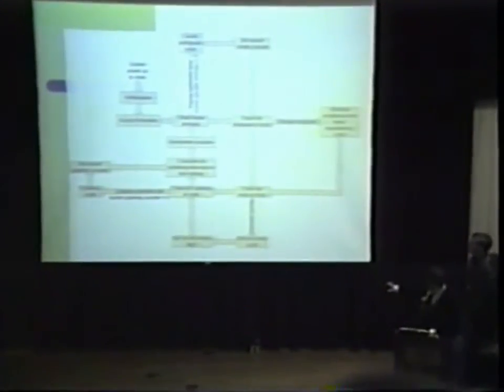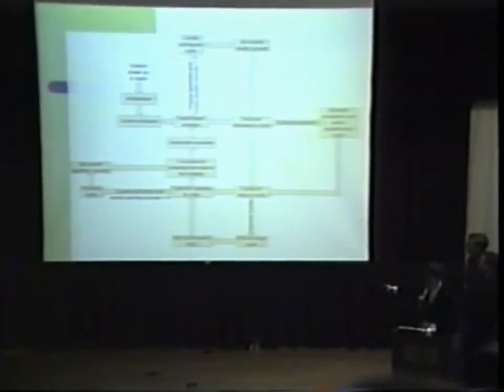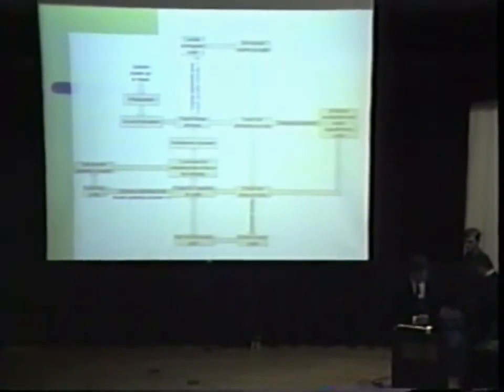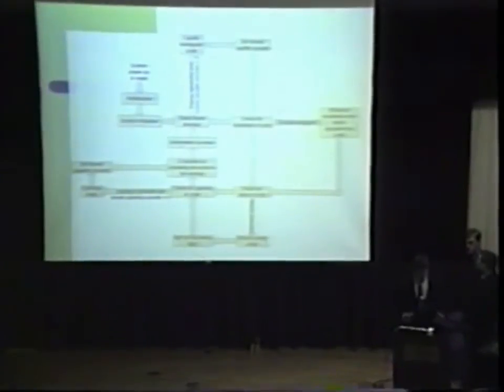And in each of these sections where it jumps off of, it jumps into other sections of code. Like here we have the candle extinguisher code. Basically the robot saw the candle in one of its distance flame sensors and it will try to move the robot close to the candle so that it can be extinguished. Then it will extinguish the candle by making small movements to ensure that our stream of water would extinguish the candle, because you need a constant stream of water to extinguish a candle.